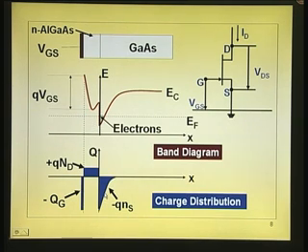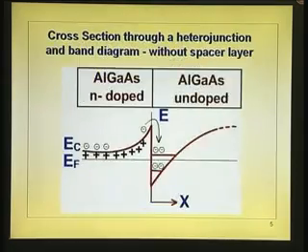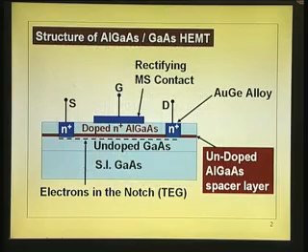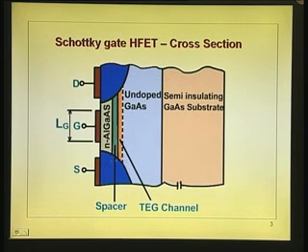If the charge is reduced to 0, what happens to the drain current? Let us go back to this diagram. Unfortunately, I have to keep on going back to that. See, the charge here is reduced if the potential drop across the forward bias is delta E c by q, and the entire layer is depleted. So, when I apply voltage between the drain and the source, there are no electrons in the depletion layer, and this charge layer is just a very small layer.